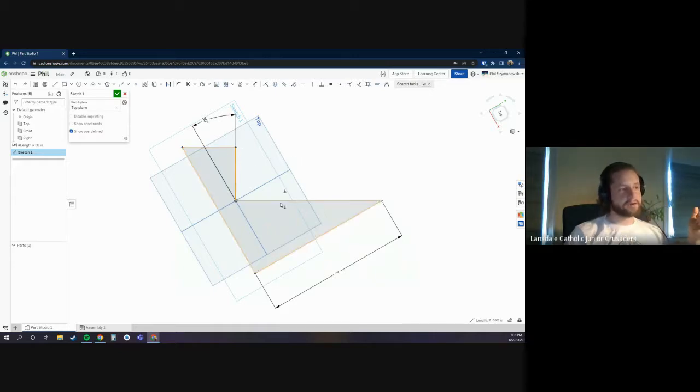And do remember, you can also just click to select lines or points. You don't always need to draw a box around it. So if you only need to select one line or curve, you can just click to select it. And the same thing goes for points. I believe when you left select or generally box select, it doesn't usually get corners. It usually just gets lines or points. So if you did want to select a point, you have to individually select points. Cool. Any questions about any of that?